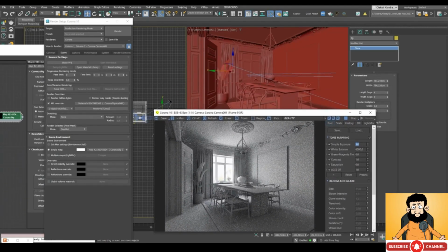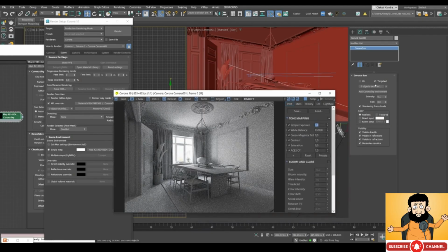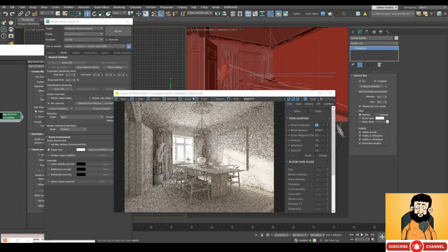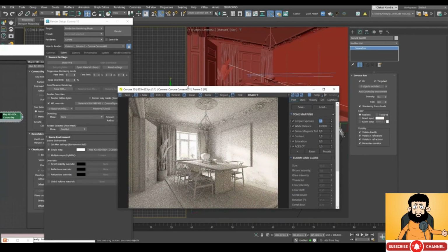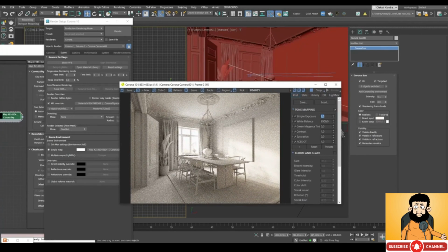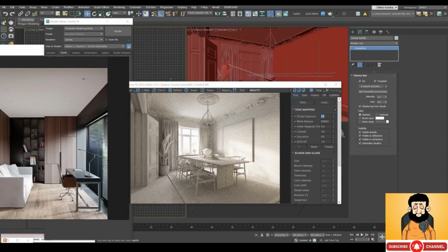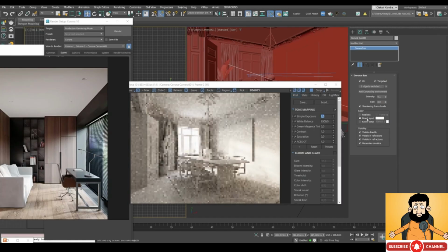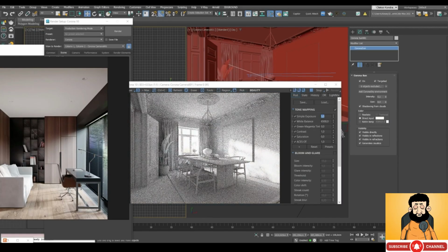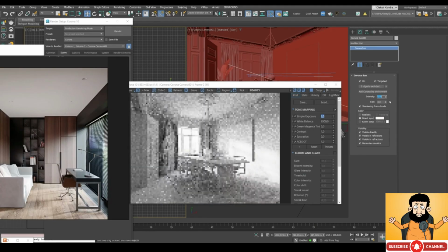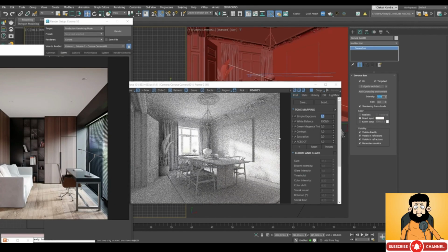And now let's go ahead and turn on the sun by checking this checkbox. And now we have a backlight and the whole scene is overexposed. It becomes very warm. To fix this, we can turn on direct input. When that's active, the color of the sun doesn't change. We can also lower the intensity value to 0.5. Here we go. Basically, this now looks like the reference.